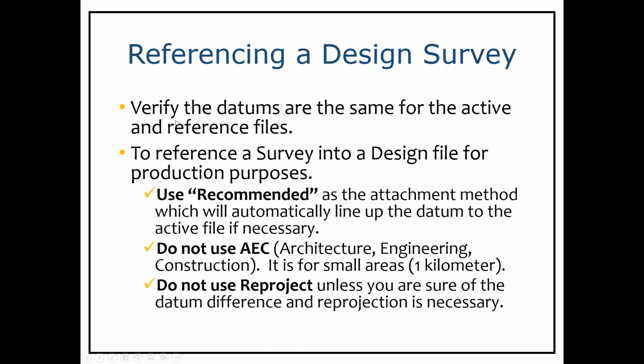Referencing a design survey: verify the datums are the same for the active and the reference files. To reference the survey into a design file for production purposes, use the recommended option when you see the pull down. Do not use the AEC, that's architecture, engineering, and construction. After studying this closely, it is only for small areas. Bentley recommends only something less than 1 kilometer, and you can match up this datum with the survey pretty easily. Do not use the reproject unless you are sure the datum difference and reprojection is necessary.